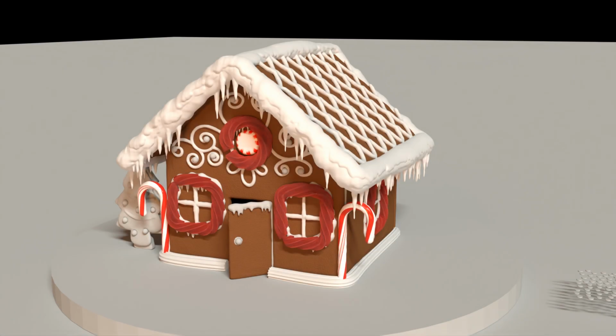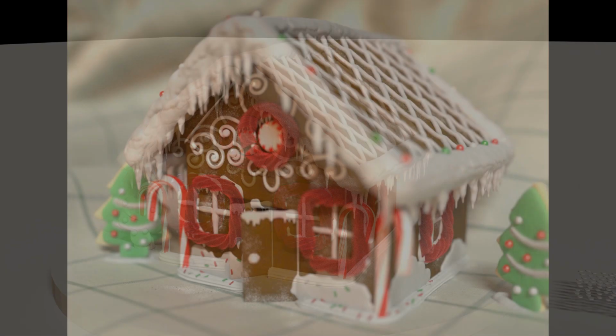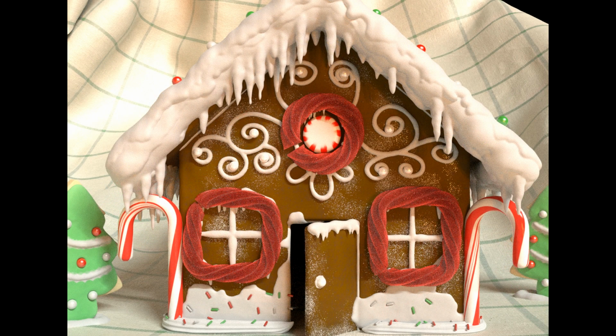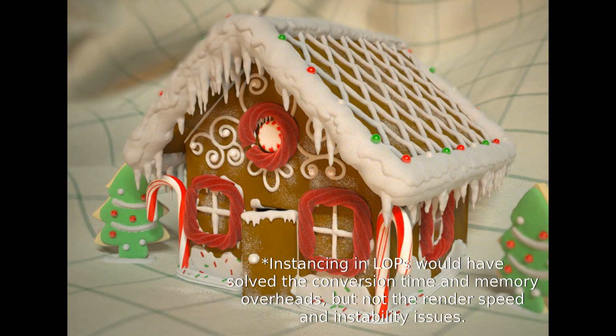My first test renders were created in RenderMan, but its CPU render was slow and made fast iteration impossible. Its XPU engine lacked support for procedural shaders and crashed Houdini a lot. I also considered using Karma, but its XPU engine was just as buggy, and it had a lot of trouble instantiating all this geometry into a LOP network for use in Solaris.